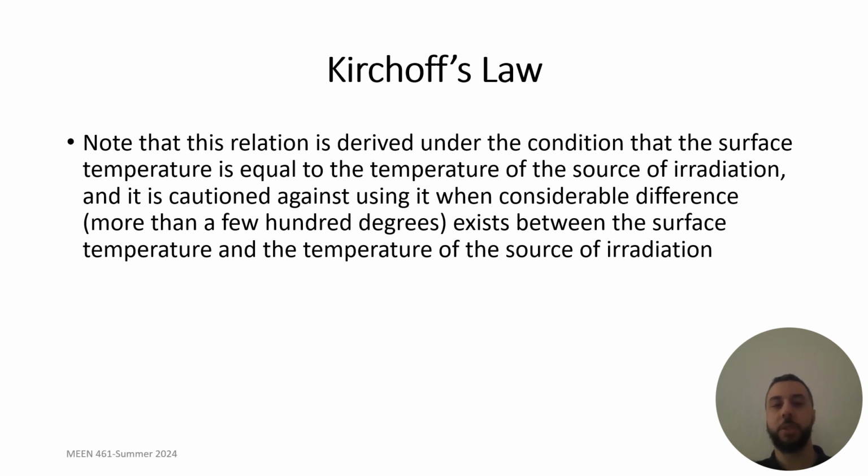So this is a simplification that assumes the surface temperature is equal to the temperature of the source of irradiation. That might not always be the case, but it's an assumption that we make so that we can use Kirchhoff's law. If there's a considerable difference, we're not going to be able to do this, but for most of the problems that we will encounter, we should have no problem doing this.